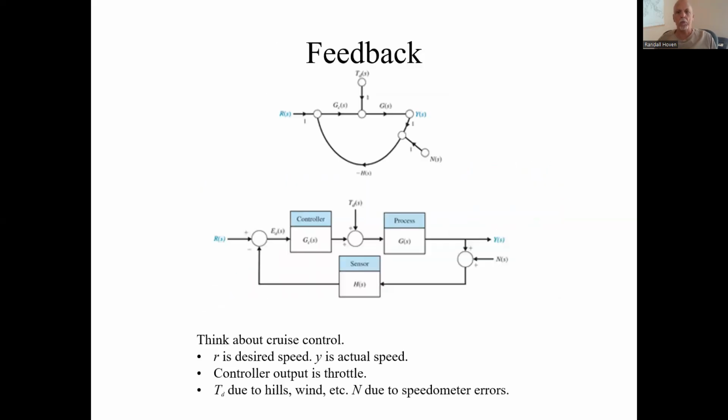And to remind you, the system we're talking about is depicted in this block diagram here. We'll have a controller, a plant or a process in the forward path, some H in the feedback path. And we have two different inputs here. We'll ignore this noisy sensor input, but we have the R that we control, and as a disturbance input we can't control. The response of this system to the two different inputs will be the sum of its response to each of the inputs individually.